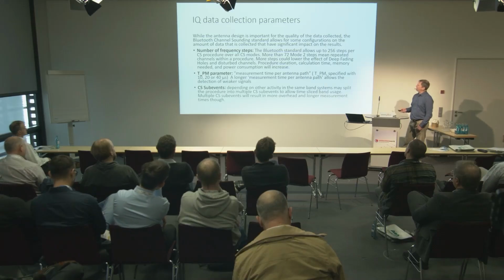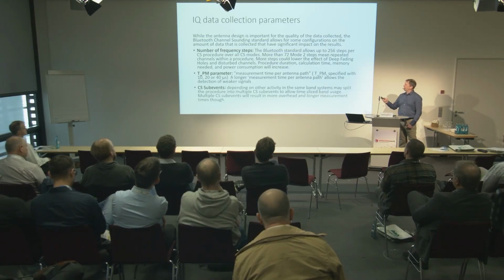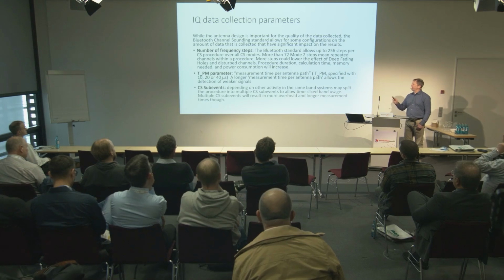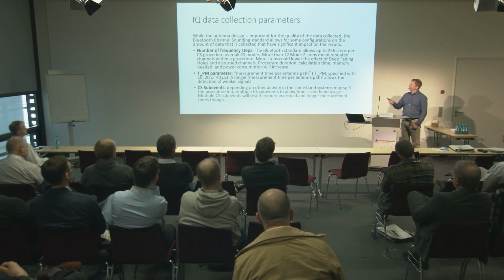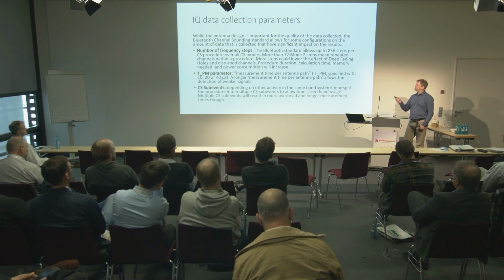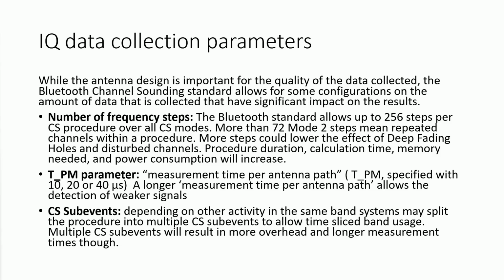The TPM parameter is how long you measure on one specific antenna path per step. This was agreed to be 10, 20, or 40 microseconds. That depends mainly on your silicon, how capable the silicon is of doing this.